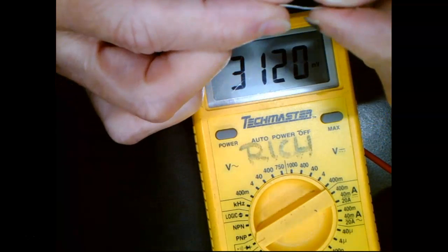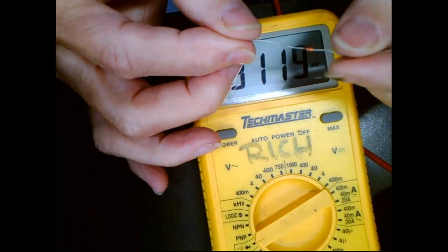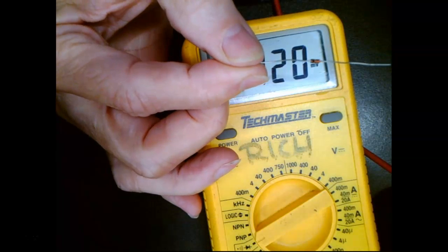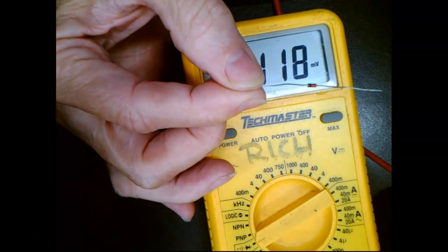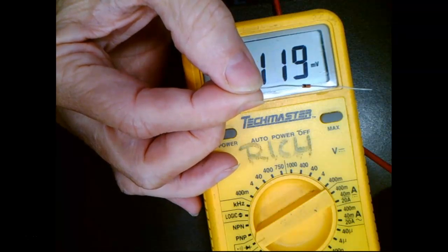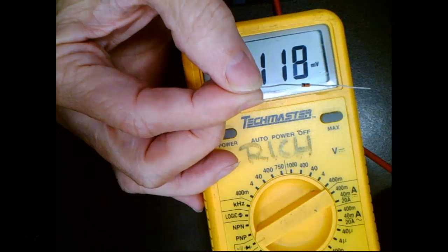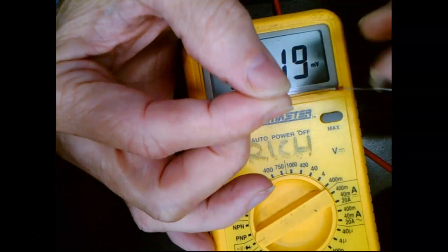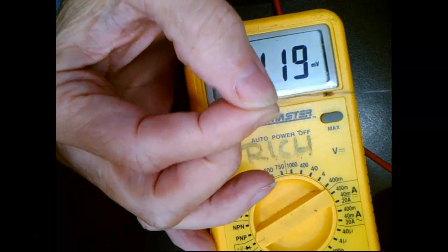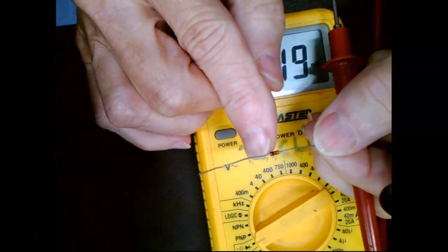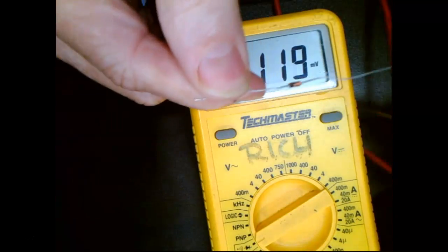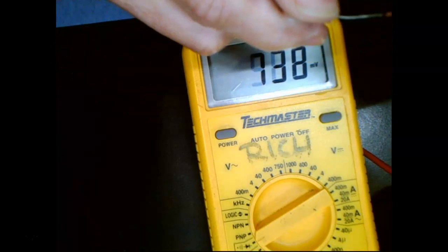Here's this one. Of course, you can tell this is a very low current diode because of its physical size. It's just like I said, it's just like water valves. The more forward current the thing can handle, the bigger the diode's going to have to be, right? So this guy right here is probably rated in milliamps. And y'all can see the black side right there. So that should be the cathode. This right here should be the anode.